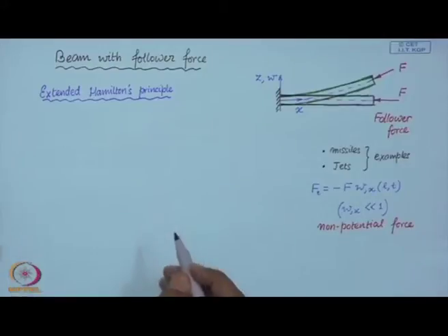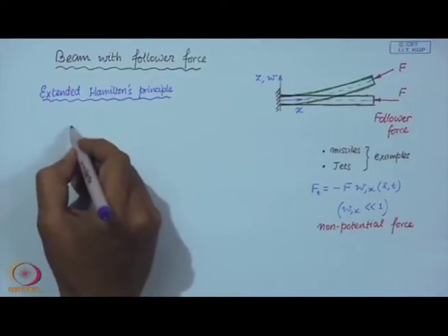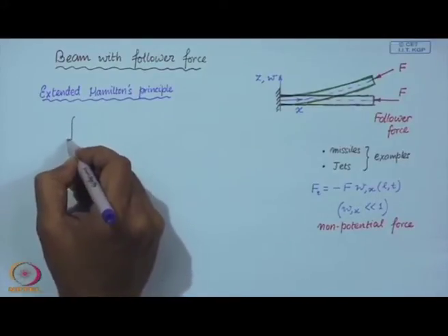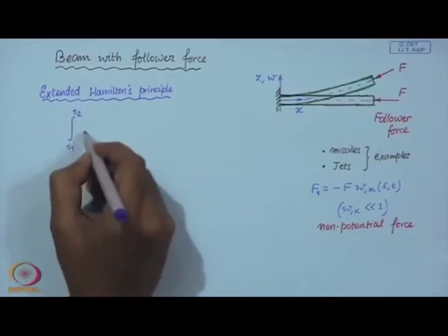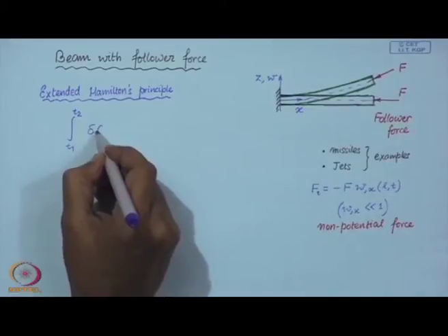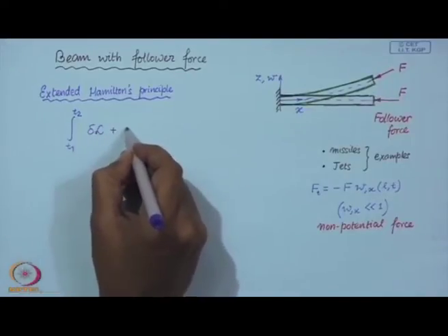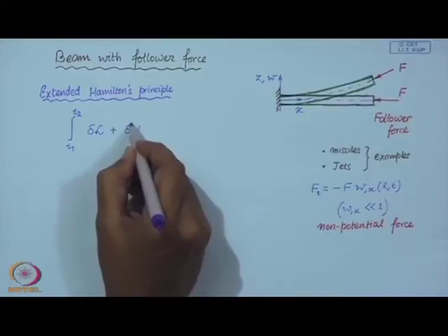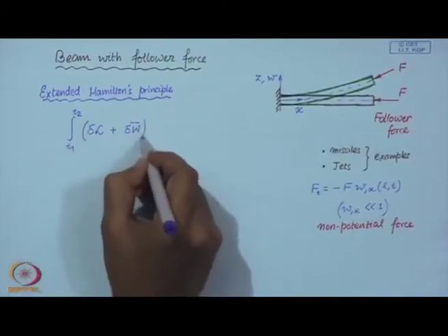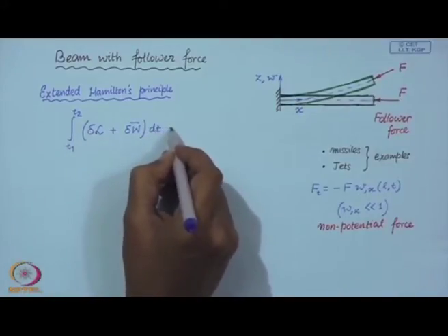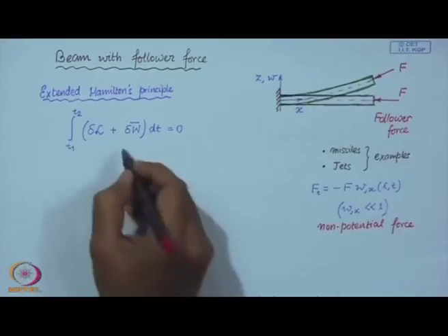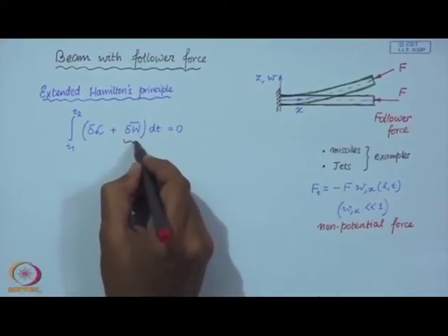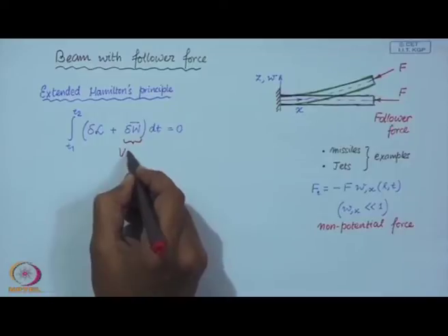So, extended Hamilton's principle says this must be 0. Here this is the virtual work done by non-potential forces.